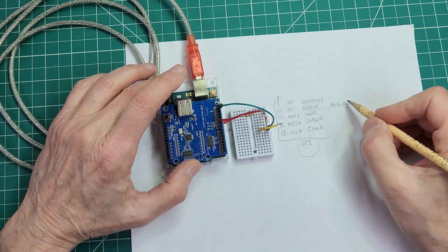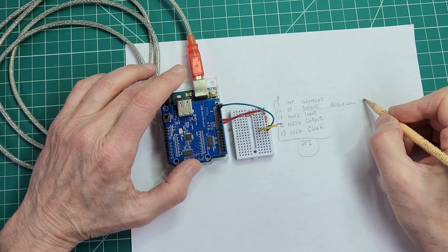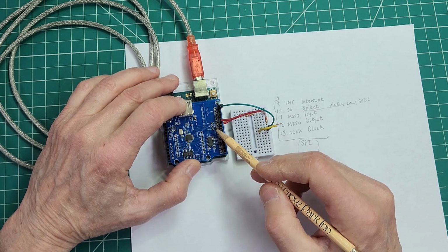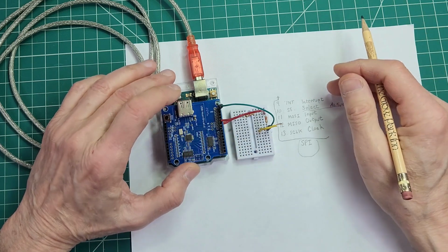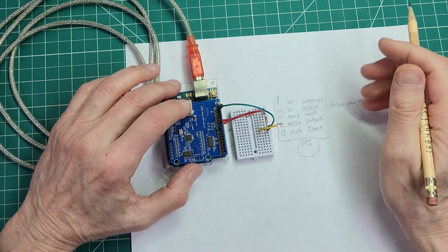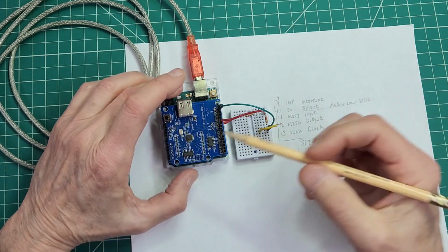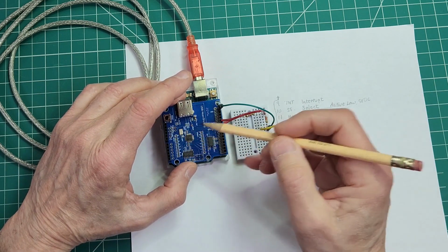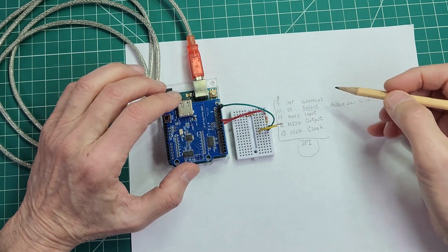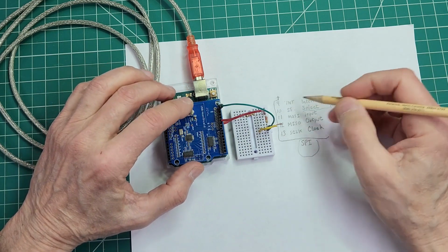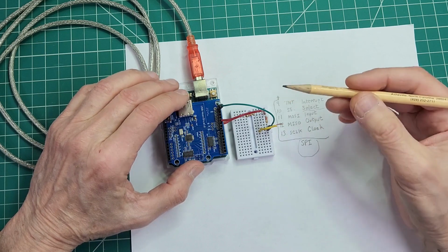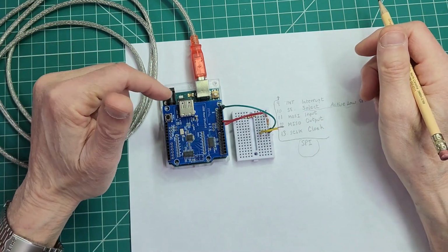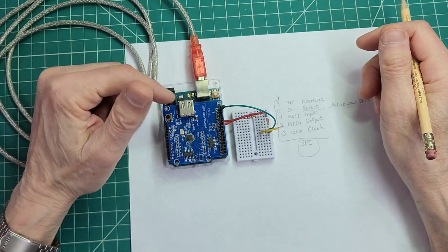So that's that 5-volt signal DC being applied to the host shield, and as was pointed out, causing a problem with the 3.3 volts on the controller chip that does the actual heavy lifting on the USB interface. So having cut that voltage down with the divider to 3.3 volts, this has become quite predictable in terms of its connections, detecting connections.